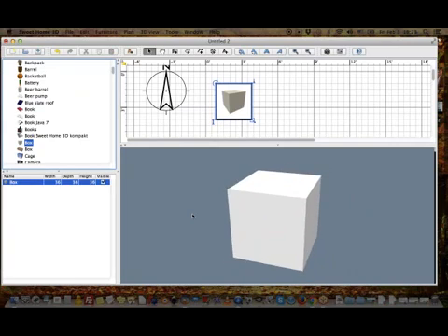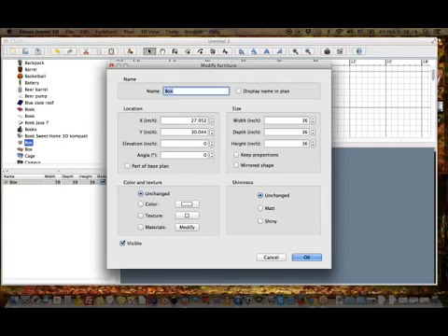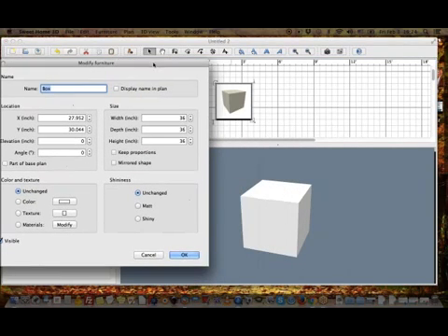Okay, it's a geometric shape that can be made into anything. Now, I am going to design a wall module that uses 2x6 lumber. So the first thing I need to do is create a piece of 2x6 lumber. And 2x6 lumber is basically a board that measures 1.5 inch by 5.5 inches, and then it's whatever length I want it to be. So I'm going to double click on this, and I'm going to say that the width, and remember the width is this axis right here, of this board is 1.5, that the depth is 96 inches,